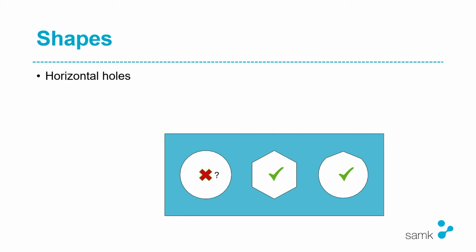If we make circular holes, they won't be 100% round. If we make a bit of a hexagon shape, which can then be drilled, of course the round hole can also be drilled to the right shape. But the hexagon in the middle can be printed without supports, because there's pretty much nothing that will be completely in the air, as the angles go to the middle.